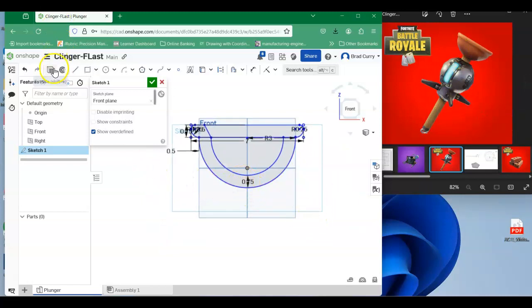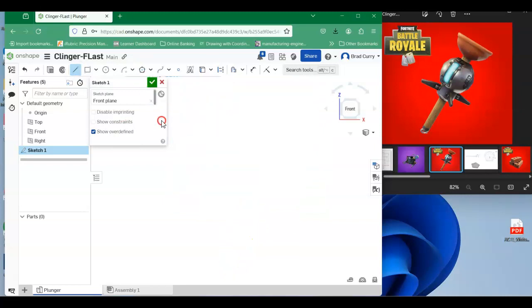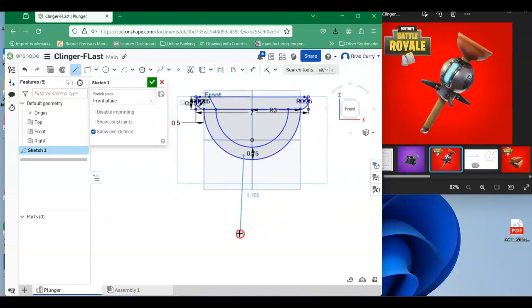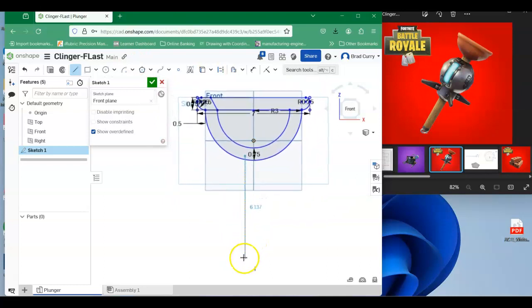So come back into the line. I'm going to do some imaginative, creative stuff. We're going to bring this in and drop this line here vertical, and right-click escape this. So let's go ahead and set a dimension of this line.